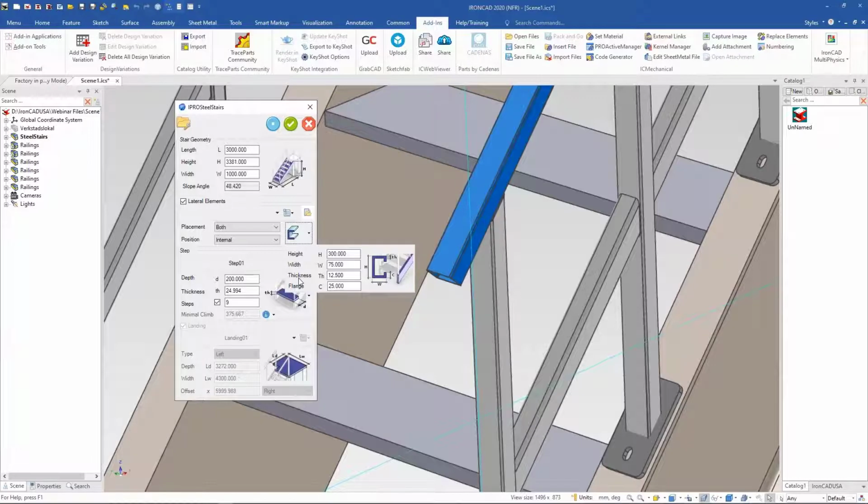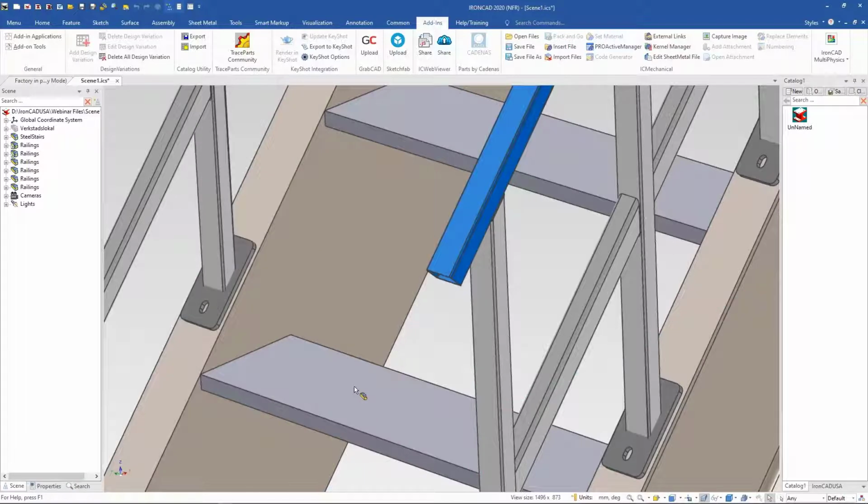Well, I know what he's looking for. He's talking about, like, here in the States, we use 1.25 inch, 1.5 inch diameter handrail. Round handrail is standard, and those aren't currently available in there. And I have been working to create some ANSI standards with U.S. information. But there's some work that you have to do to make sure that attachment points stay correct, etc. Okay. But we'll work on getting some answers on that, definitely. Great.